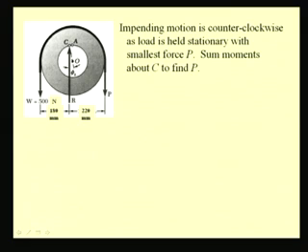So the point of contact, which is originally at A, now shifts in the counterclockwise direction to a point C, where the horizontal displacement of this reaction R is equal to the radius of the static friction circle, which is again 20 mm.